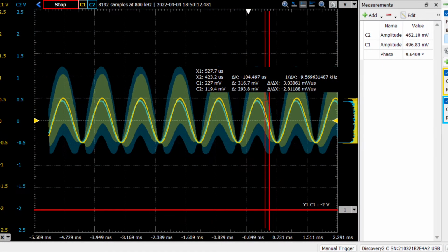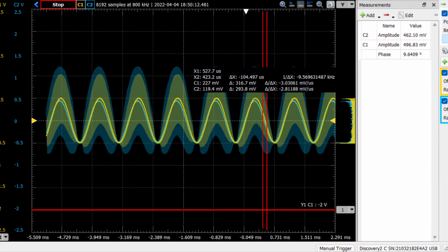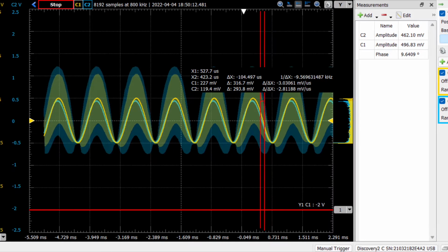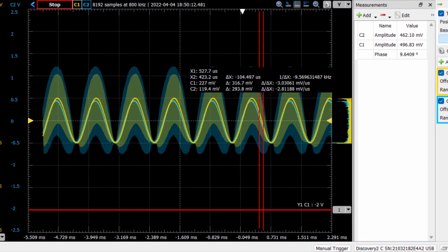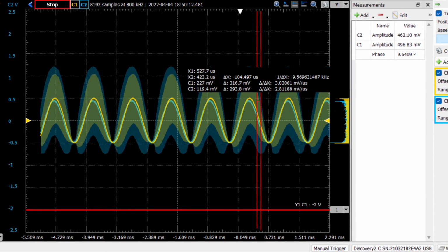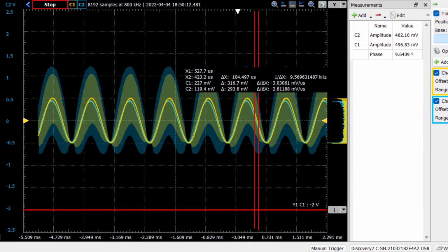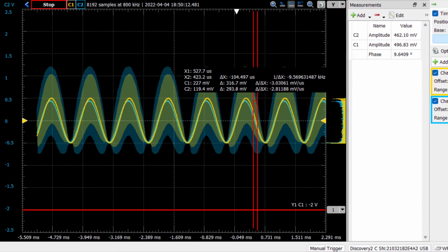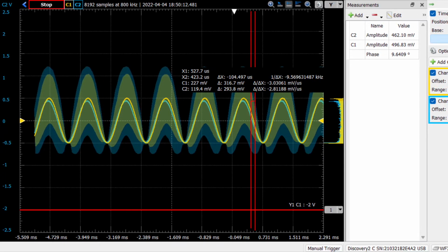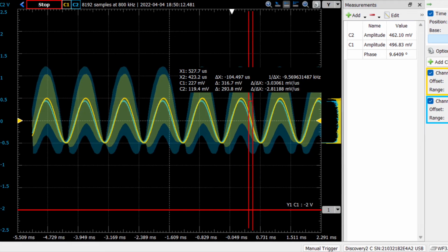In the next simulation I did, which was the waveform measurements, I decided to plot channel 1 and channel 2. The 1+, which was for channel 1, was connected to the input voltage, and the 2+, which is connected to channel 2, was connected to the output voltage.